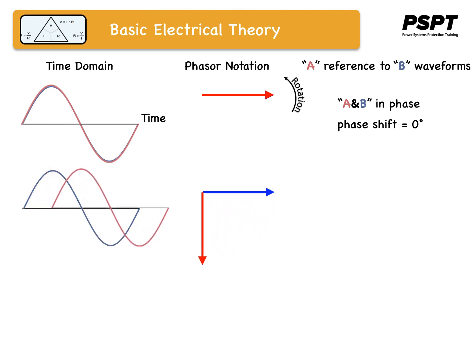In this example, you can see that the phase angle of the red is straight down and the phase angle of the blue is from left to right. And you can see what has happened with the time domain graphs as well. In this case, we say, because the rotation is counterclockwise, and that is a standard that we usually adopt in the analysis worldwide, the rotation is usually assumed in a counterclockwise direction.